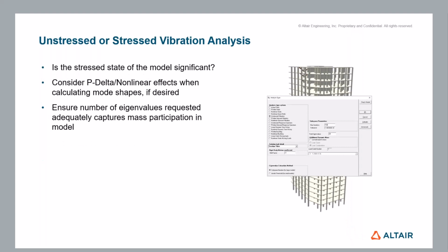We also have the question of, do we want to run an unstressed or a stressed vibration analysis? And the question I always ask here is, well, is the stress state of your model going to be significant? It's somewhat hard to quantify. But what this analysis allows you to do is consider P delta and nonlinear effects when calculating the mode shapes. An example of this might be if you have a large compressive load on your structure, the structure may be close to its buckling limit. And at that limit, the vibration characteristics or the dynamic characteristics are going to be different than if it were pulled into tension, for example.